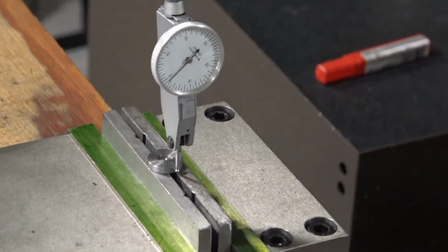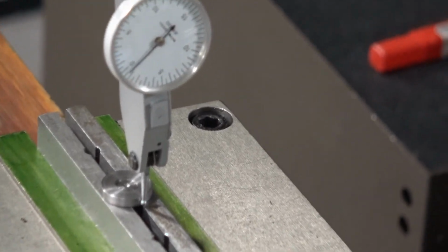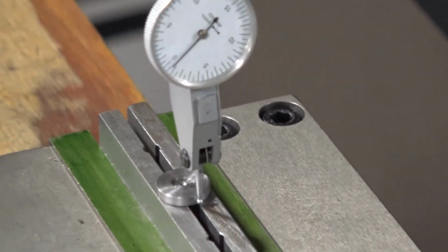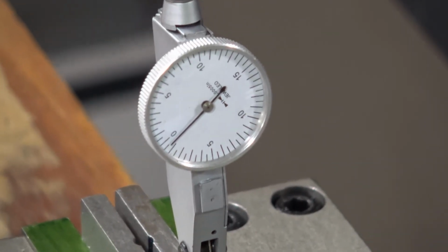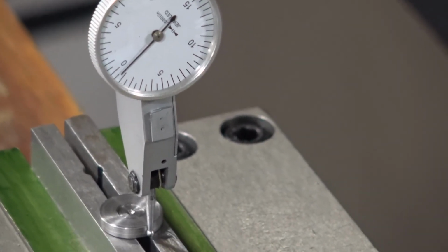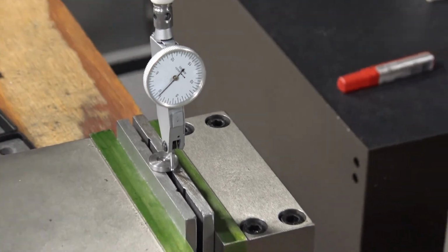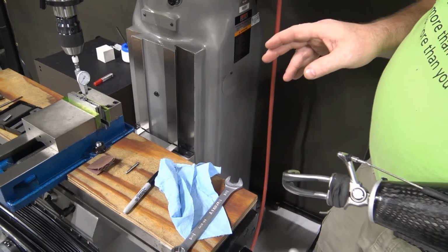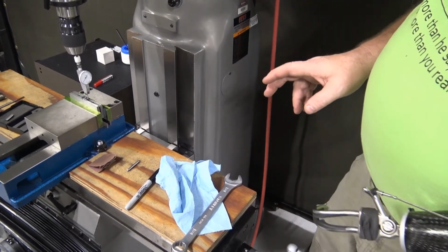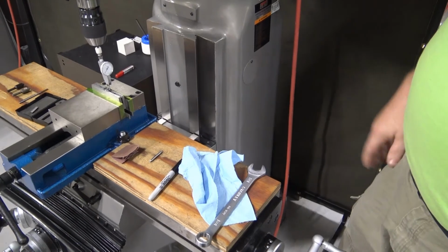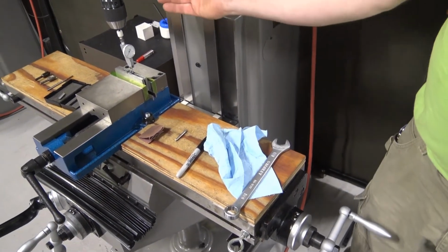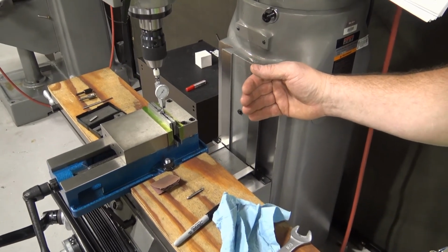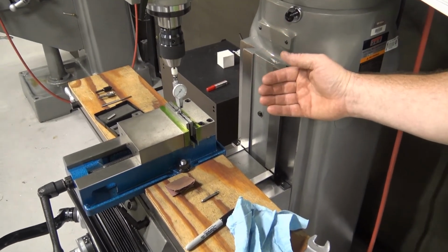And as we get 180 degrees apart, my two readings are roughly within 1/1000th of an inch of each other. Well, because my position of that offset pin needs to be held to a tolerance of plus or minus 1/1000th, I need to make sure that I indicate this thing to way better than 1/1000th so that I can control that offset distance. So because my 0 and 180 degrees, if you will, are both matching at 0,